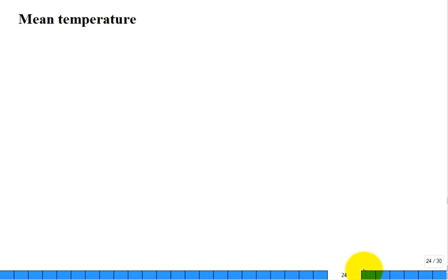All right, what about this mean temperature? How did we get the equation for the mean velocity? We had something simple, then we had some integration. And so if somebody says, I want you to calculate the average energy flow down a pipe, you'd say, well, I need to know the velocity at that location, so u is a function of r. Thinking about a ring again, here's that ring. They have the same velocity. I'm going to also say in that ring it has the same temperature.